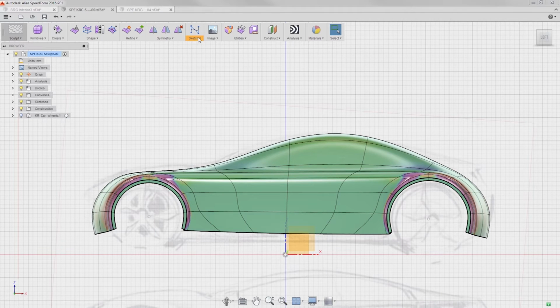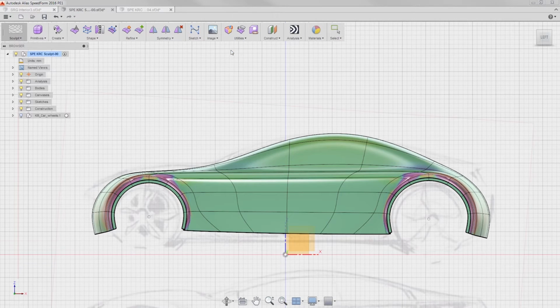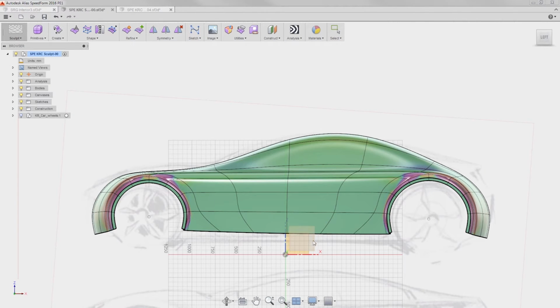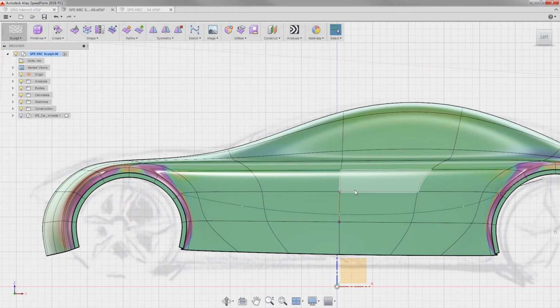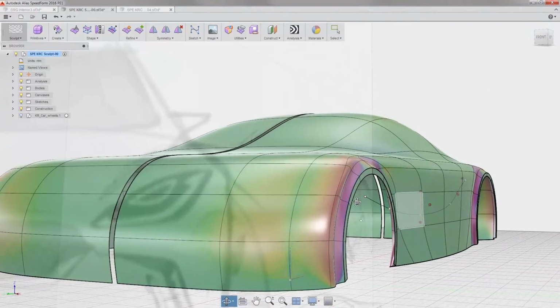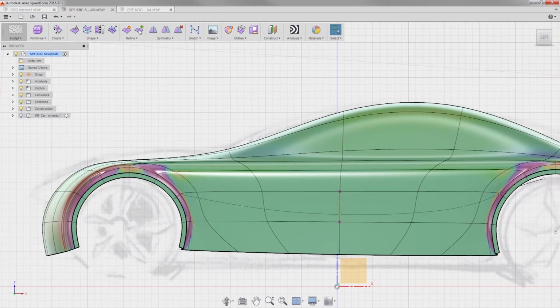I'm going to create the sketch using this spline curve. The CB curve could have worked as well, but this curve has to be planar. I'll form the shape of the curve. Now I'll take a moment to make sure that the curve is flat against the plane. If it is not planar, recreate the sketch.